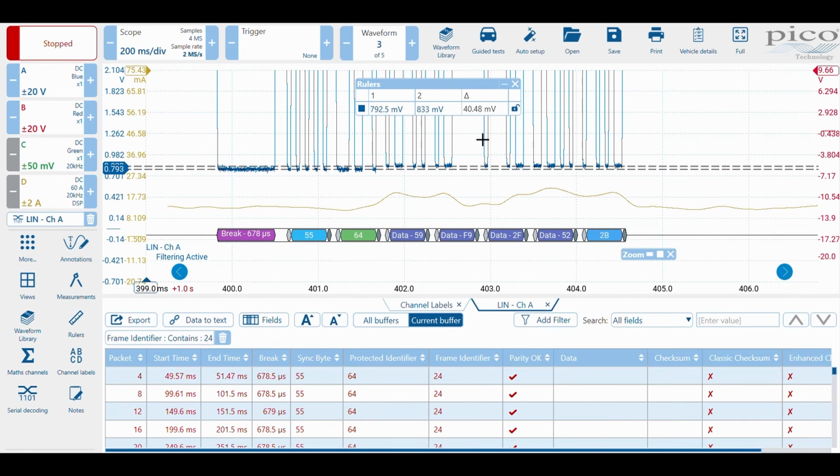If I add a deliberate resistance value into the ground of that switch, that voltage drop should increase, and we'll see a difference. We may even see errors. So what I'm going to do now is add 750 ohms of resistance in the ground wire to the air conditioning switch, and let's see how those results pan out.